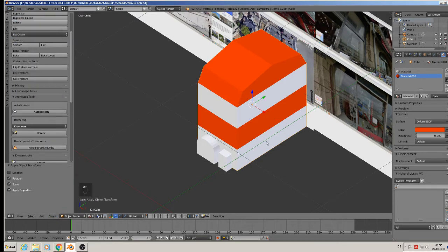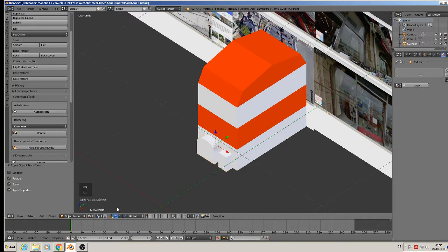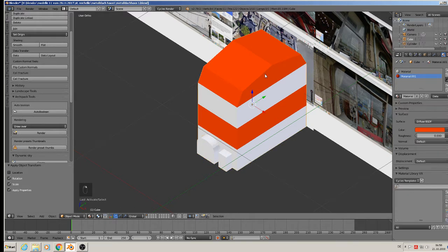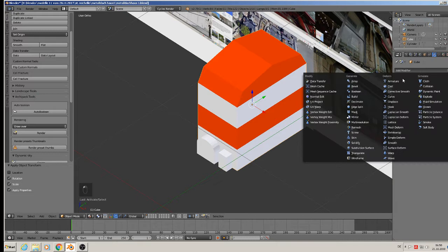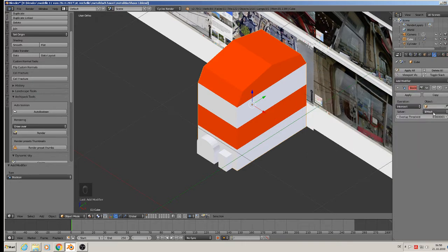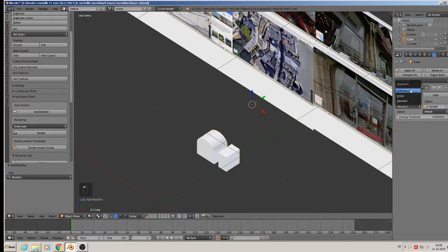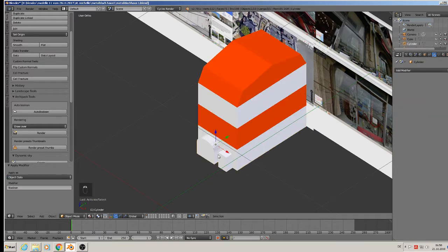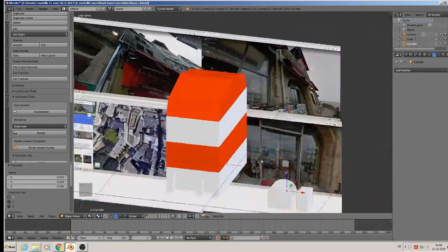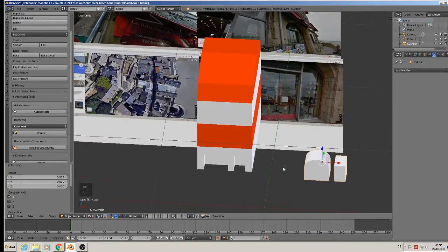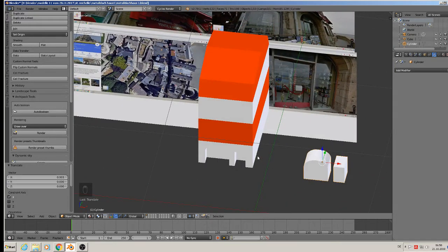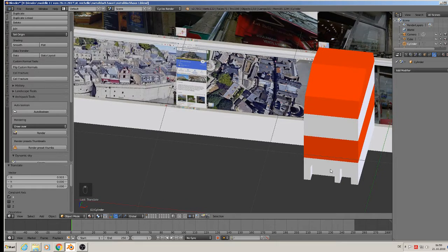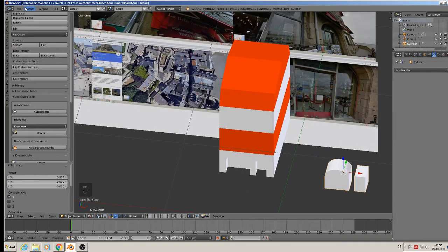File, save. Then we click on it, the name is cylinder. We go to the house, modifier, take a boolean, say here cylinder, and it should be the difference, apply. Doors are cut in. Good. So we have done the first one, file, save.